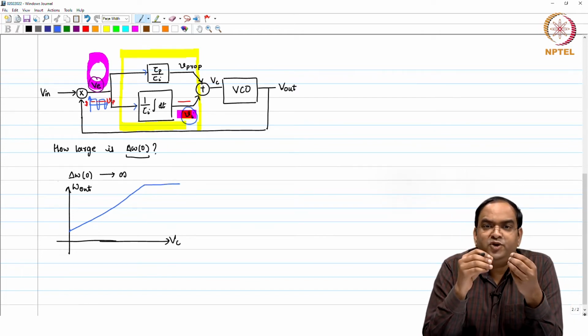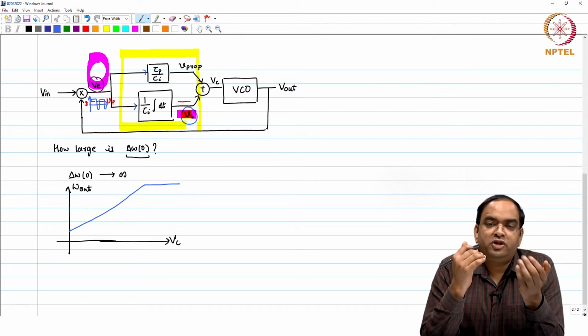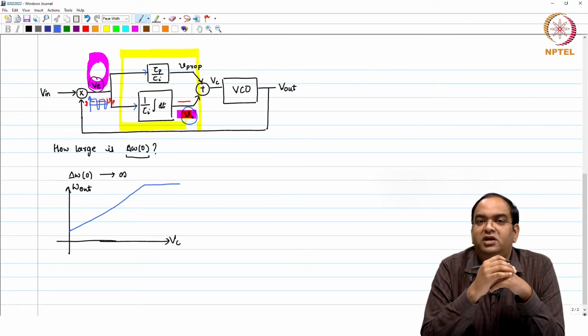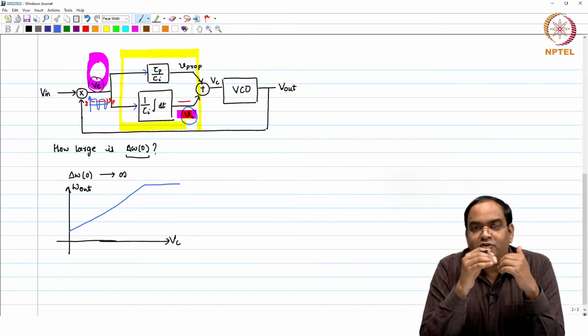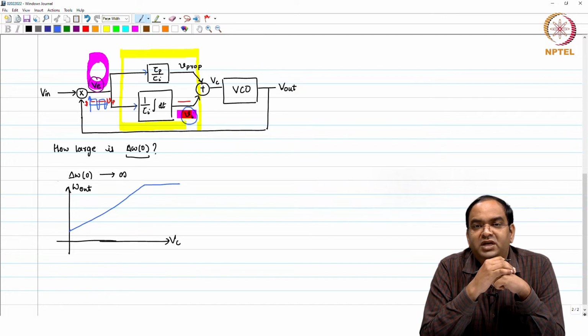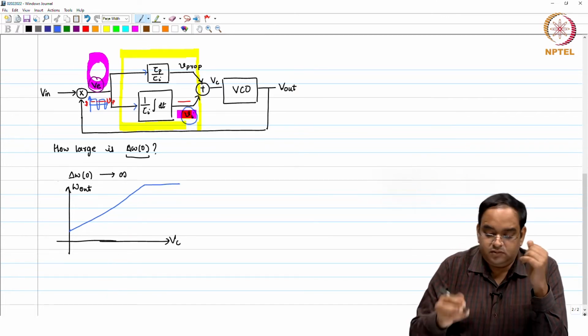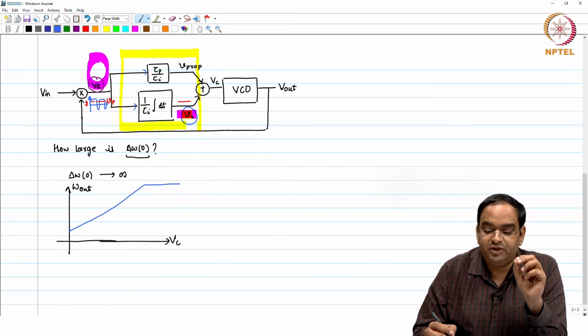At the end of the day, you will design these oscillators and all these blocks in a given technology. You know that you cannot increase the voltage beyond a certain value in a given CMOS or BiCMOS technology. So, your frequency is always going to be limited by that at least. So, this loop itself does not put any restriction on the output frequency.